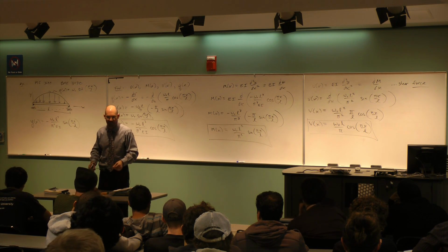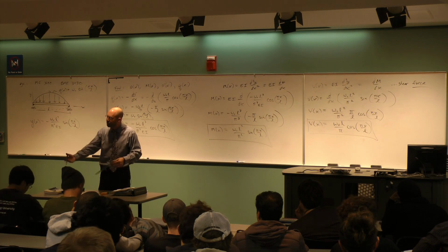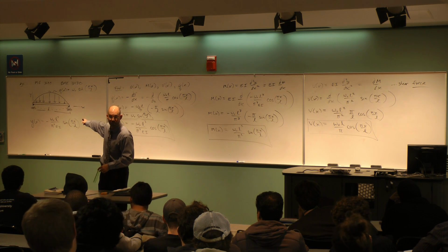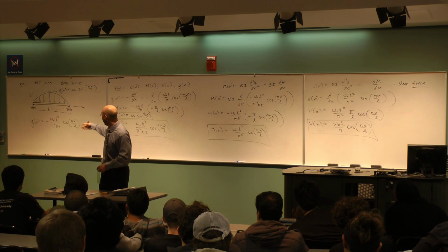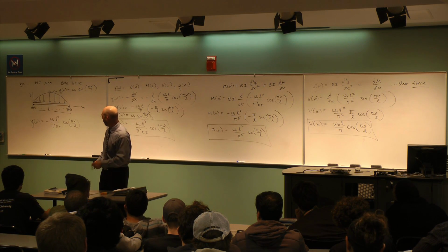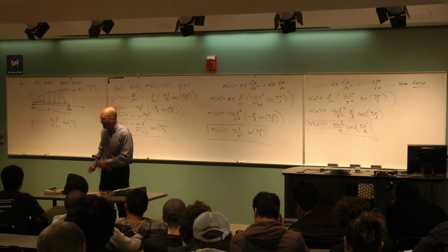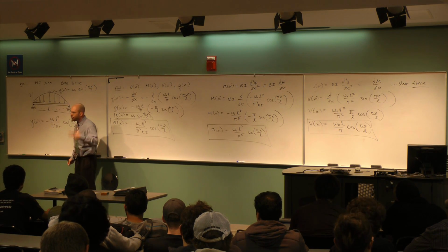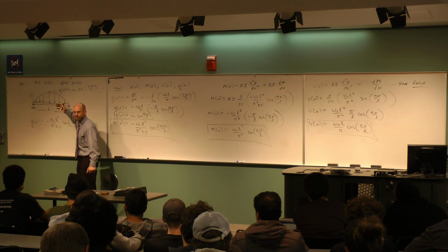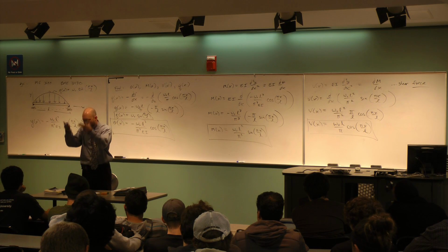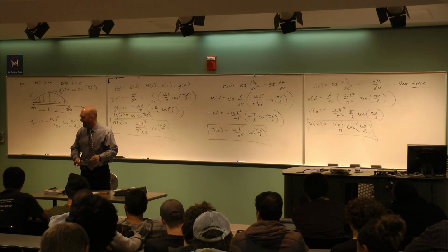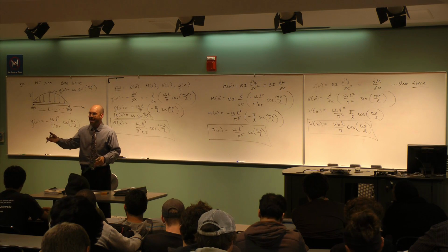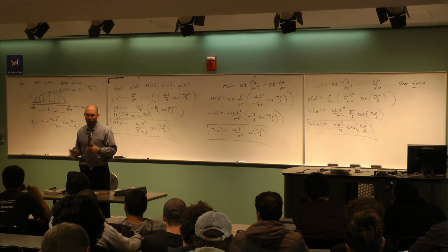Because we're asking you to be an engineer. So just look at the picture and say, does it make sense with my math? If I've got a beam supported like that, and I asked you to calculate the deflection at x equals L, and you got some number like, I don't know, W naught L to the fourth over pi to the fourth EI times 12, is your answer right or wrong? It's wrong because it's pinned at this point. Forget your math, just look at the picture. So in the end, I hope the math on the test helps you sketch the picture correctly. If the sketch that makes sense to you agrees with your math, you should feel happy at the end of that problem. If your math is like, there's no way the beam does that, then if I were you, I'd feel disturbed.